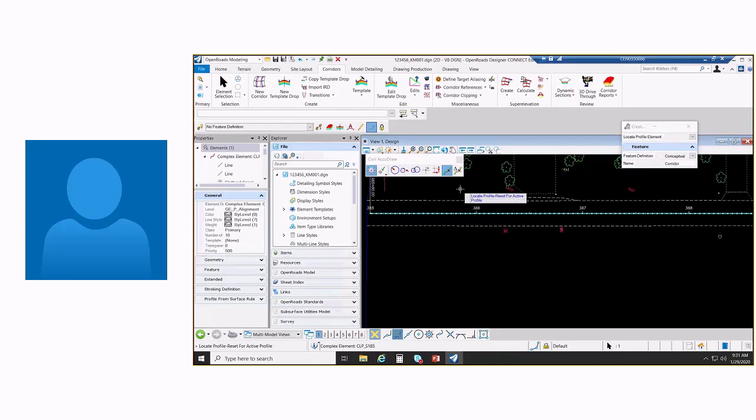If I needed that existing ground to be a named profile, I could have used the profile from Surface command to make one, and it would overlap the terrain displayed profile. So I hope that makes sense. But anyway, I'm going to use the active profile. I'll right-click, and the name of my corridor here, I'll just name it planing.